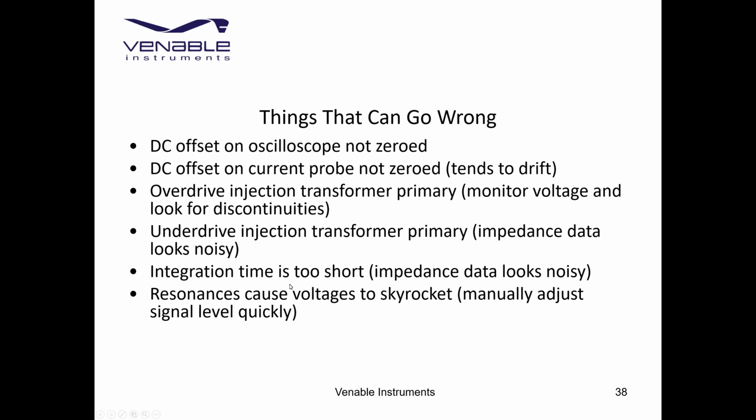And I had problems, at least with ISS, with the input filtering on some of their units, which had a lot of really high Q resonances. So you could get into a great deal of trouble if you injected too much signal. You could over voltage or get a distorted measurement.